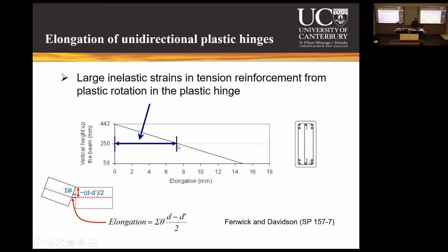So in the mid section of your member, you will get an elongation, total elongation, which can be quantified by this simple formula, which takes into account the accumulation of rotation. And this was given by Richard Fenwick and his research team back in the 90s.